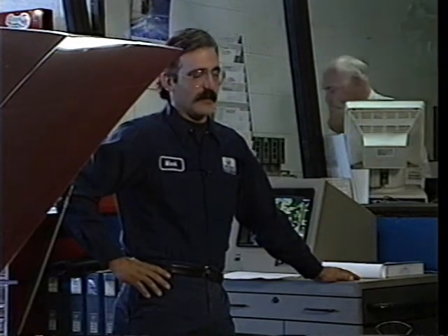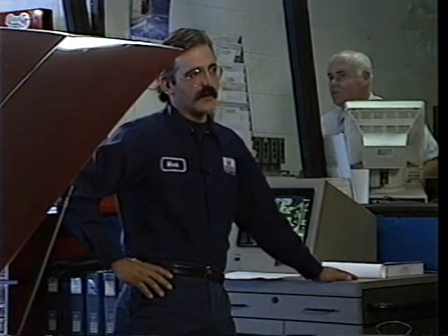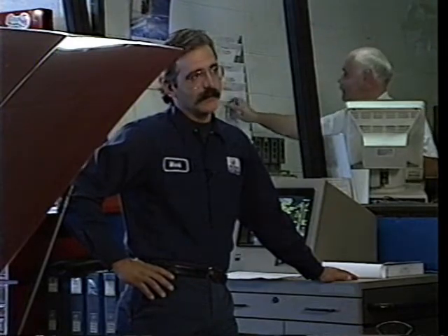And with the VSM hooked in and recording, all the driver has to do is press the button and it records the time that the problem actually occurred, and you can come back to the shop and look at the screen and play it over and over and over again until you finally see what really happened. And sometimes it's just more helpful eliminating things that are not the problem.